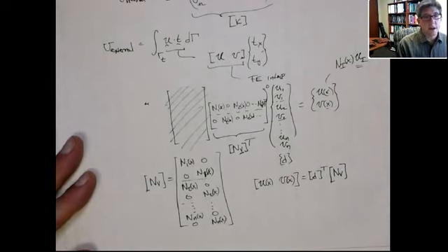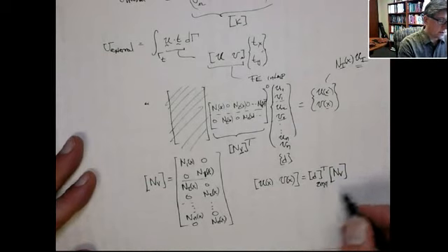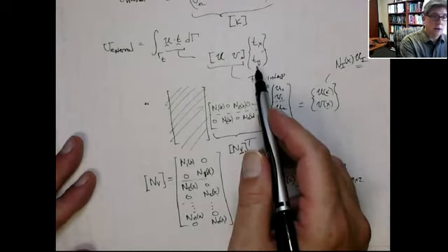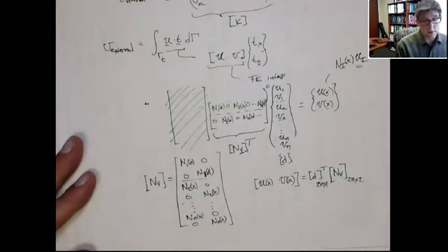And you can see the dimensionality that works out, right? This is a 2n by 1, and this is a 2n by 2, and then that's going to get dotted or contracted with the traction vector, which is a 2 by 1. All right, so the dimensionality works.